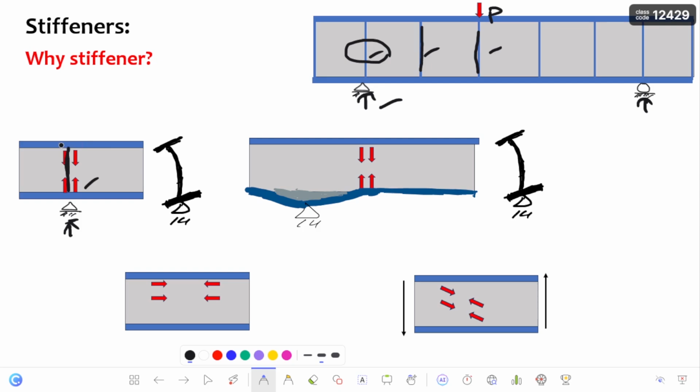This is one of the important reasons why we are providing the stiffener at this particular bearing location, or you can say higher shear concentration regions. Here you can see this is the buckling profile of the plate girder. And next, coming to the other thing, based on the change of shear force or bending moment diagrams, we can provide taper sections across the length of the plate girder.